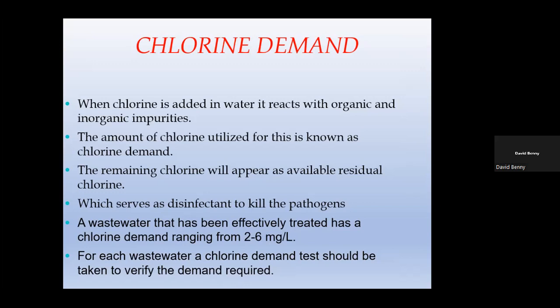Now, in the streams of wastewater treatment, the most effective technology today is variations of the activated sludge process. Because you have that process, you can withdraw at least 96 to 98% of the available BOD. And if you remove such an amount of BOD, then what is left of the organic constituents is hardly much more for reaction to cause a demand.